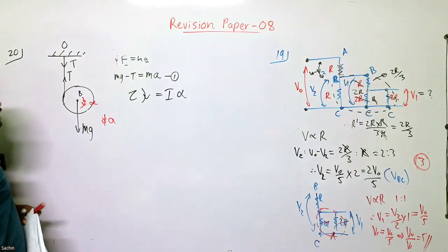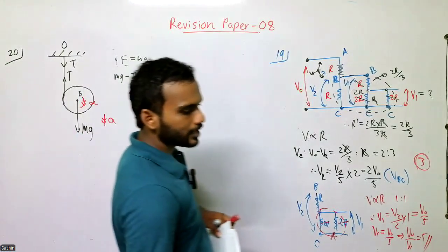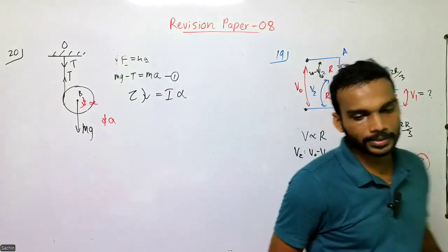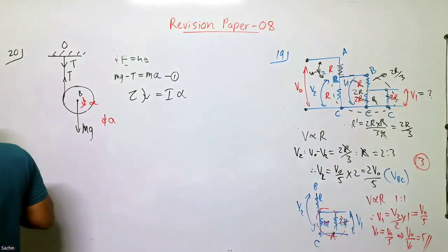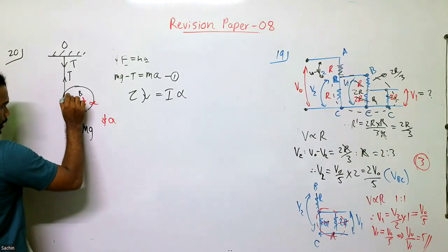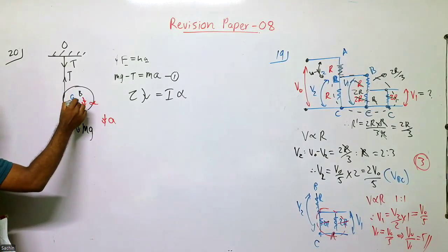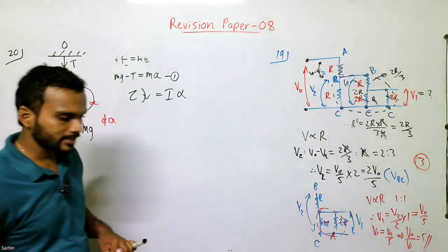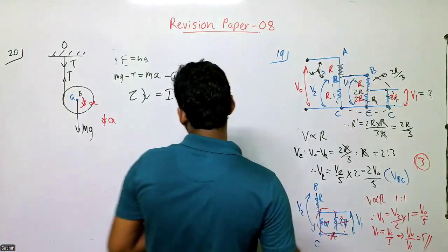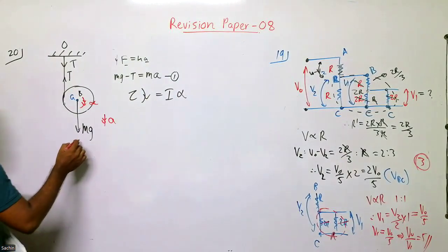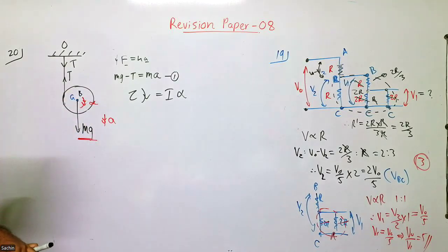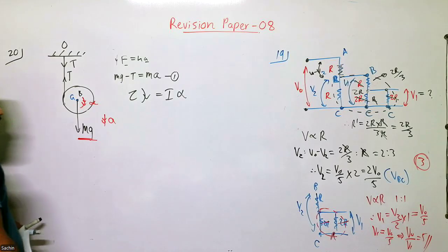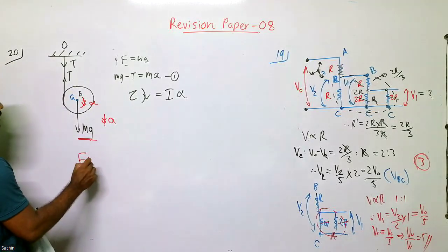When you apply that, what force builds up the required torque? That is the question, right? Remember, when we are considering the circular motion, you just have to identify that this circular motion occurs around the center of gravity at this point. So what is the force which can exert a torque about that point? Can weight exert a torque? No, right? Weight can't exert any torque around the center of gravity. Why? That is going through it. So if the line of action goes through the point we consider, there will be no torque. There is no moment because the perpendicular distance is 0.